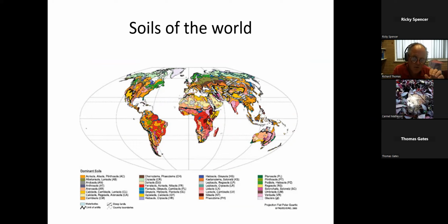Now, don't just think all soils form like I just showed you. Some of them are then transported alluvially. So a lot of the soil on the campus or on the river farm down towards the Hawkesbury, it's rock that's been transported a long way, and then it got caught in the river bend and it just settled out. So the soil that you'll get in a particular area does not necessarily relate to the local bedrock if it's been transported by alluvial transport, and that could have happened either since the last ice age or the previous ice age, or it could be due to glacial deposition.